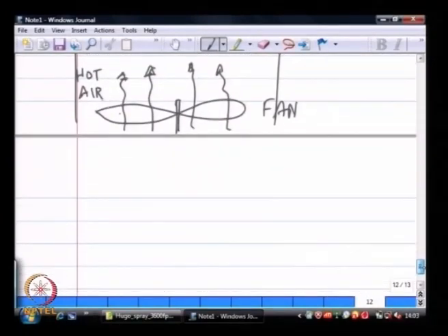As a result, I could get hot spots very close to the nozzle itself. So, I do not desire complete pulverization of my liquid, I want some large drops in there as well to give me this flame geometry. I want the flame itself to have a certain discernible length associated with it. So, these sorts of conflicting requirements you will see in every one of these applications, and we will talk about how to resolve them as we go along as well.